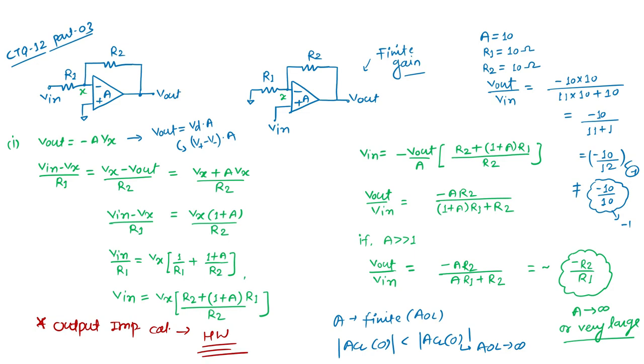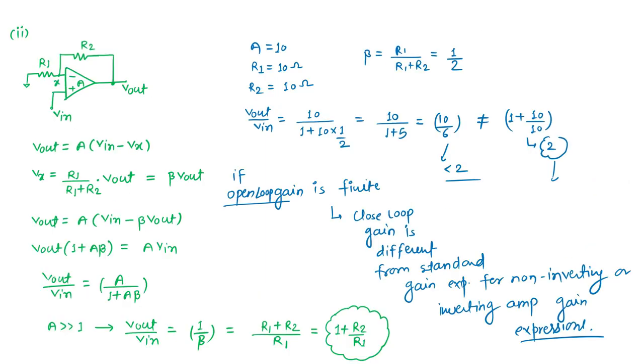Just put a test current source or a test voltage source. If I put a test voltage source, we can observe the current, and we can also apply a test current source and observe the voltage. Either way, we can calculate the impedance at any node.